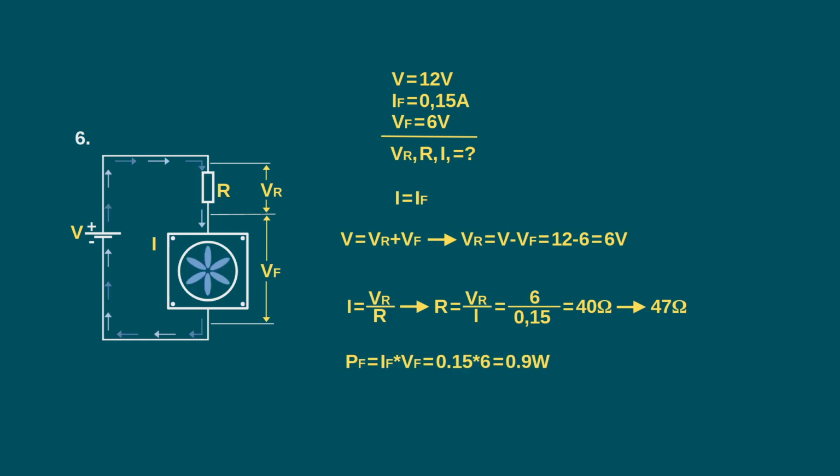Due to the total power of the fan, we cannot choose a standard quarter or half watt resistor, because too much load would quickly damage it. Therefore, the most optimal solution is to choose a 2 watts resistor. Then we are sure that everything will work properly.